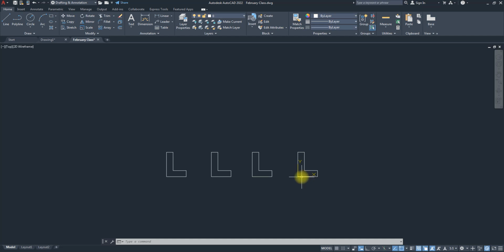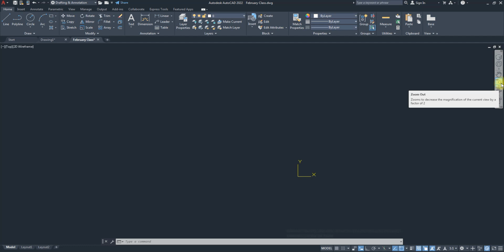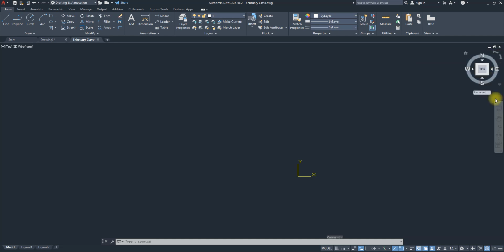So what we're going to do now is delete all of them and try to do the H. We might not do all the shapes and all the different types. Maybe for the H, I'll do absolute. For the E, we will do the relative. Then we can go and practice other ones. So I'll change this back to my world coordinate system. We have moved the UCS icon. So for the H, you help me. Let me turn off this dynamic input.